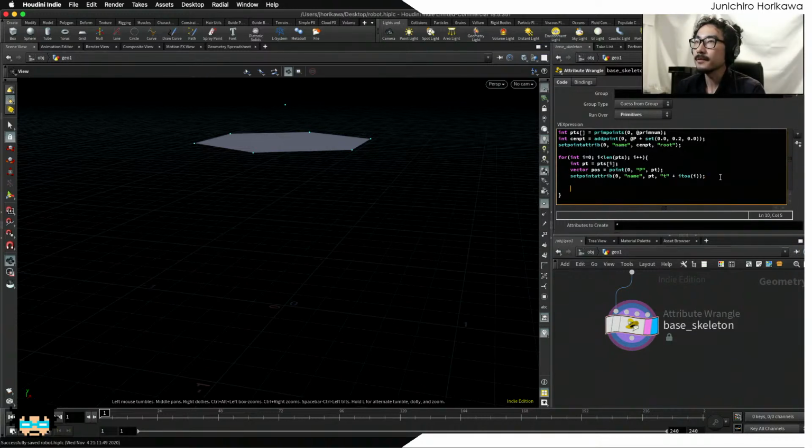Now let's create a primitive as a polyline, so that I can create a polyline connected from the root to each point. So int prim equals add prim as polyline, and for initial curves I can add this root, which is cent pt, together with those points on the vertices, which is this pt.